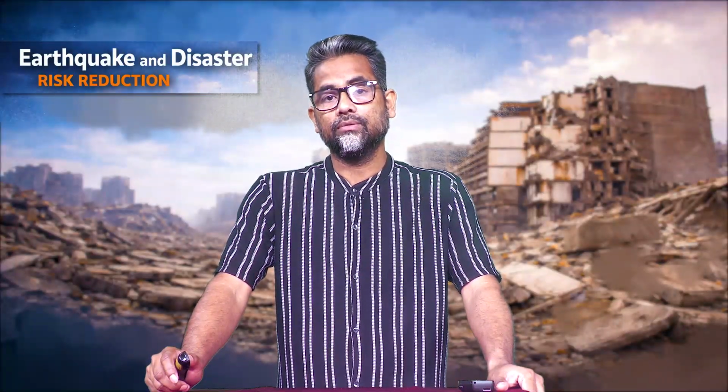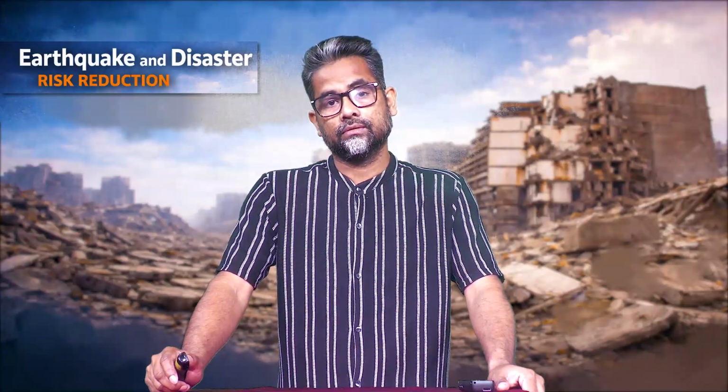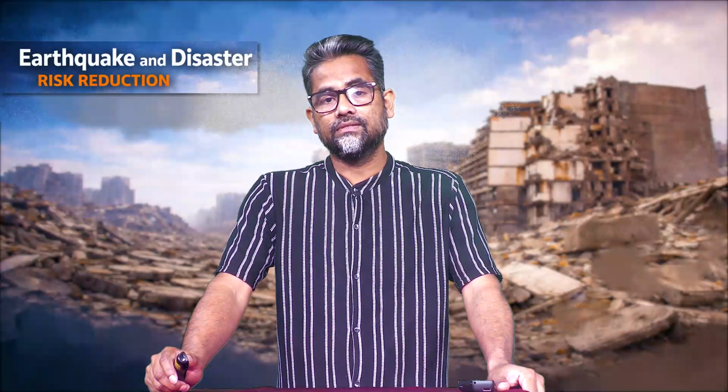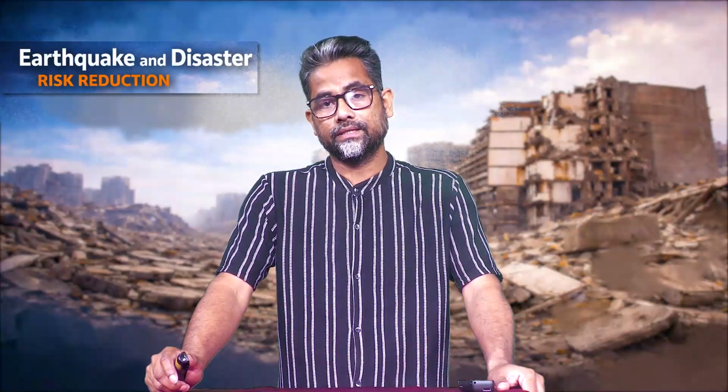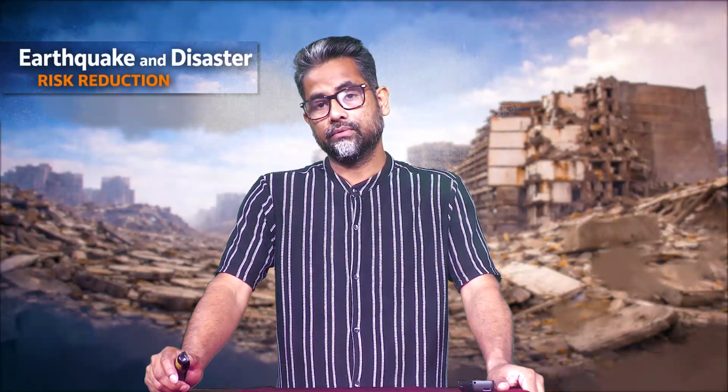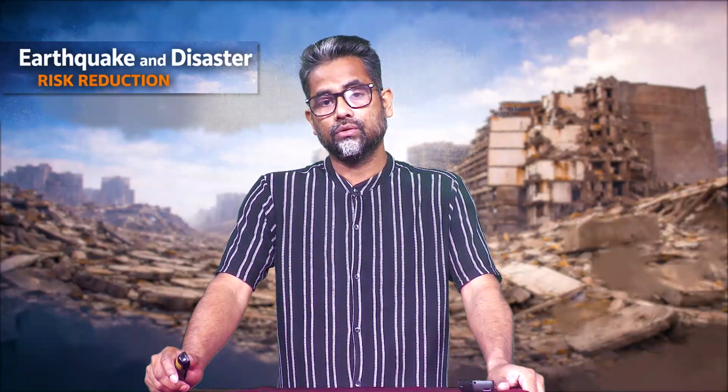While the vast majority of earthquakes in India are natural, certain human activities can induce low magnitude seismic events, usually with a magnitude less than 5, by altering subsurface stress conditions. First, reservoir induced seismicity, that is RIS. Filling of large reservoirs increases pore pressures and stress on underlying faults, triggering small to moderate earthquakes. For example, the Koyna Dam in Maharashtra is one of the best known cases of reservoir induced earthquakes globally, with recurring earthquakes since the 1960s.